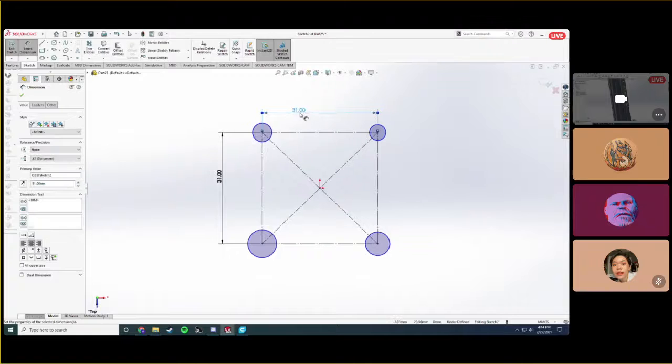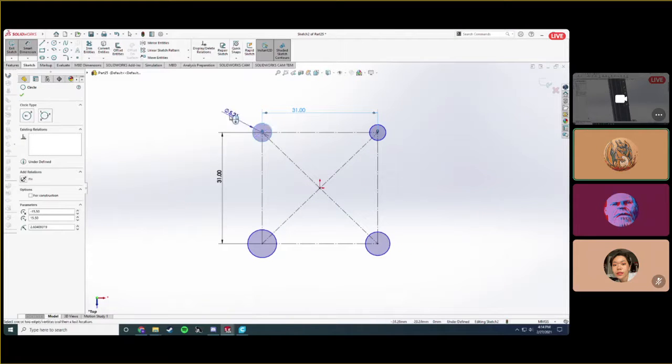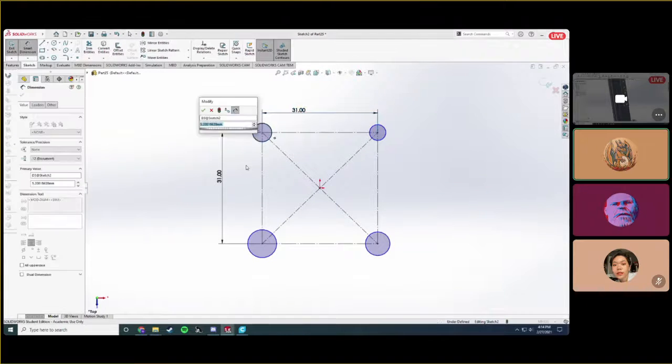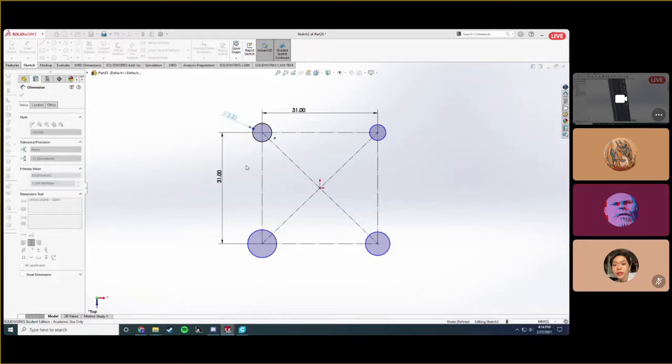And then, off my memory, I'm pretty sure these were 3 millimeters, but make them a little bit more, so, let's say we're going to 3D print this piece, just give a little bit of room for error for the screws.